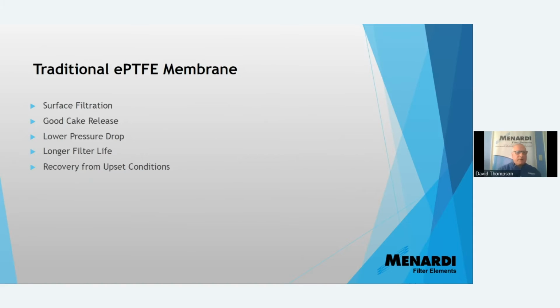Traditional ePTFE membranes, like low drag or LD membrane, are surface membranes. However, because the surface is inconsistent, you get some entrapment of fine particulate. You do get good cake release off of traditional membranes. There's no doubt about it. Versus a regular bag with a dust cake on it, you do get very good cake release and good cleaning. However, not as good as you would with the low drag.